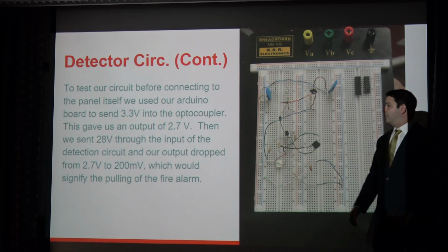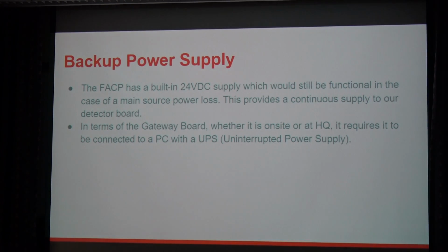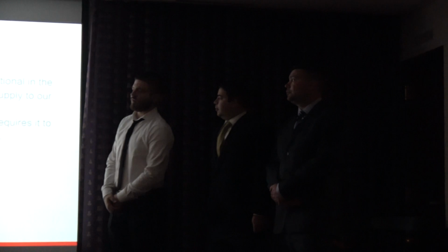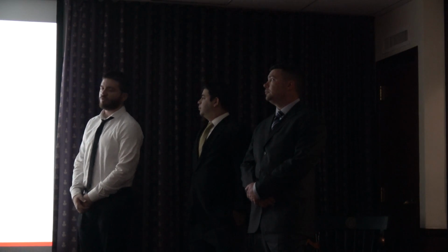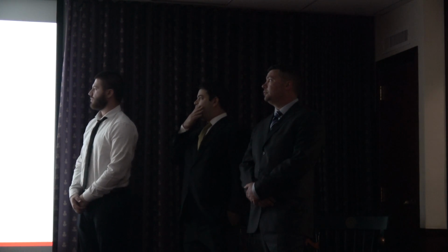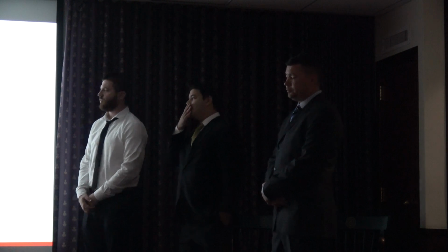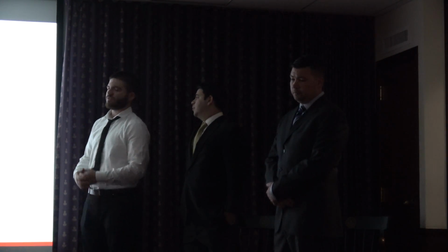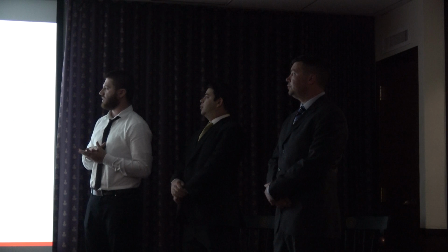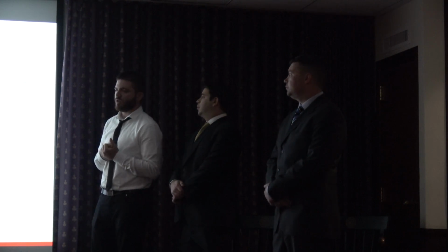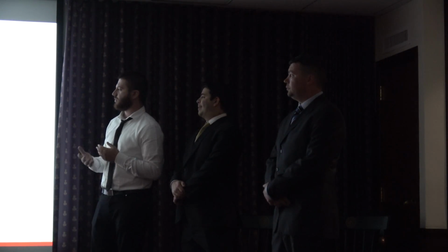Just to quickly go over the backup power supply. Luckily, our fire alarm panel has its own built-in 24-volt supply, which provides a continuous supply voltage to our detector board. But in terms of the gateway board, we have to consider that it's connected to a PC, so it needs an uninterruptible power supply to be able to keep on.